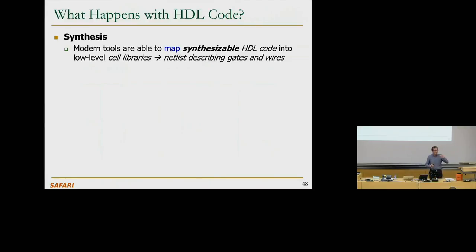You have some hardware description. So somebody also in the break asked the question, will the circuit that's generated by the structural Verilog code be the same as the circuit that's generated by behavioral Verilog? Not necessarily, because behavioral Verilog is at a much higher abstraction level, and the synthesis tool may actually take that abstraction level and pick different gates to satisfy the specification in the description. Whereas if you already specify the gates exactly, the synthesis tool will take those gates and basically generate the hardware for you. Okay? So that's the difference between behavioral versus structural. With structural Verilog, you can clearly define your circuit at almost the lowest level.